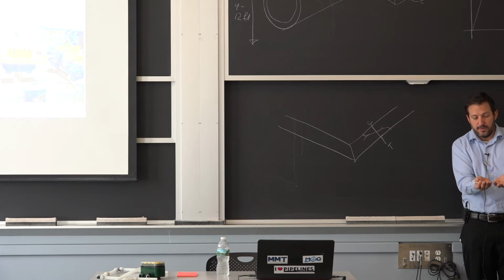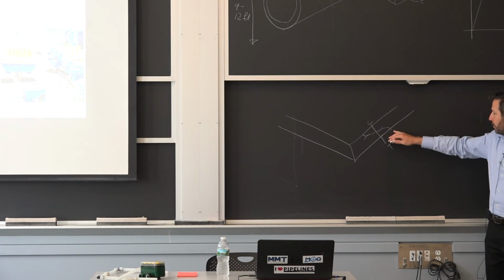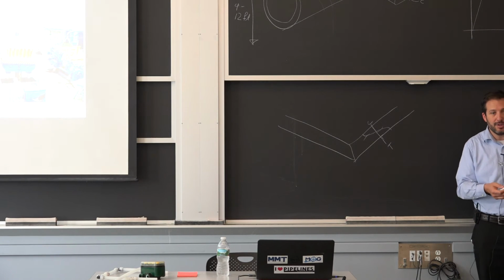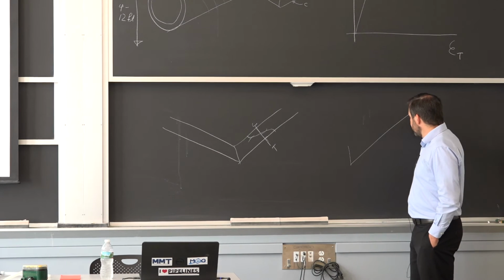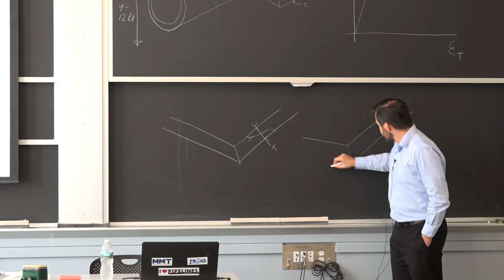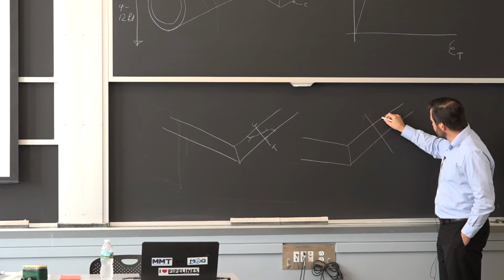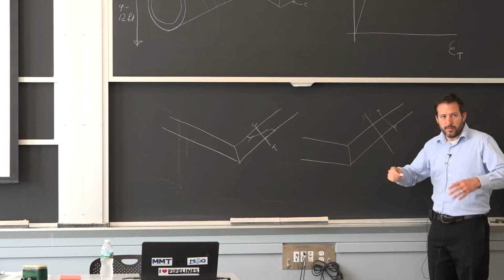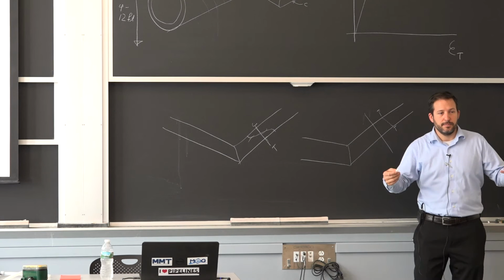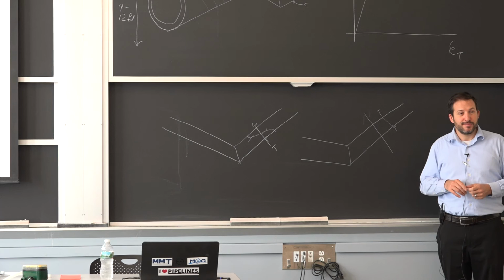That's what gives you your springback. So if I try to stamp something, it's going to form and then it's going to come back a little bit. So it's a very complex process to get a precise shape, and I have residual stresses. What the aerospace people do with stretch forming is they get almost everything to be in tension. There's going to be a very, very small difference in tension because it's all being pulled, let's say 2% strain. So when you unload it, there's no stress.